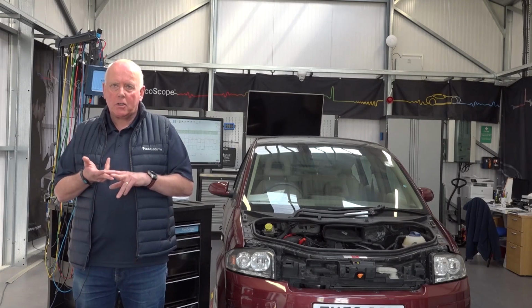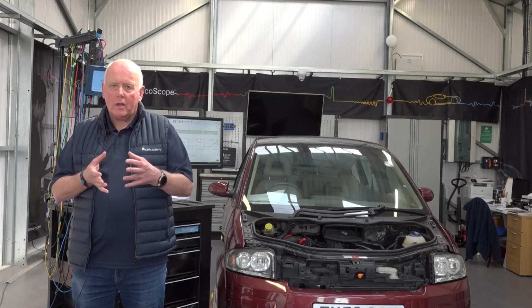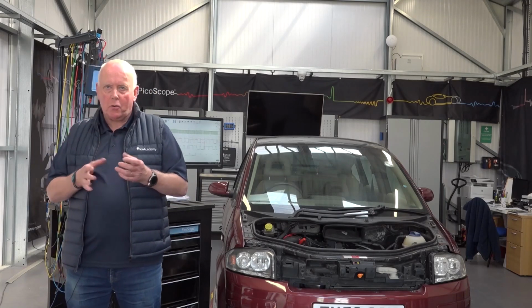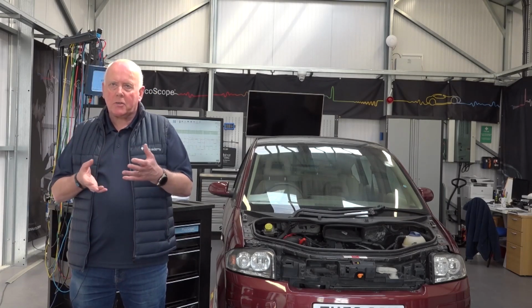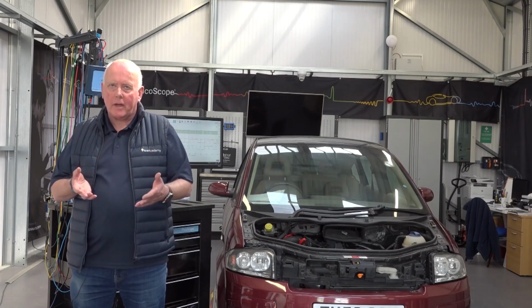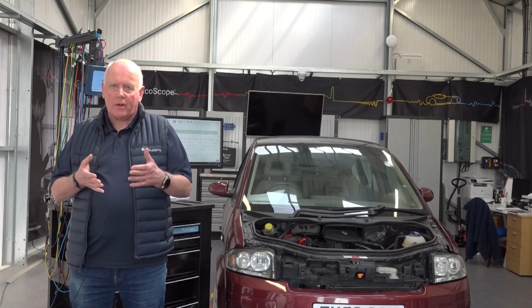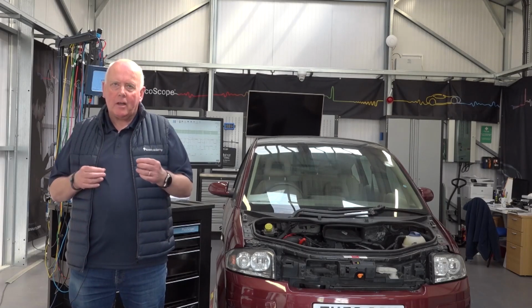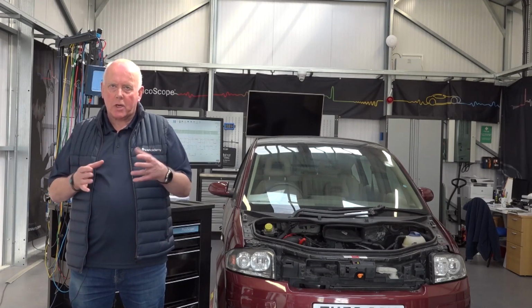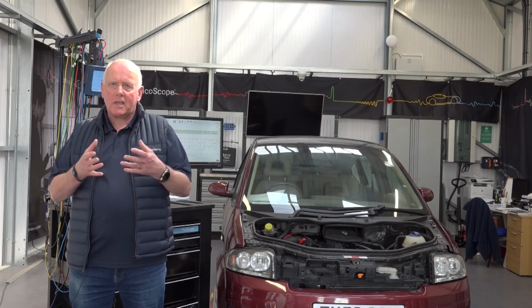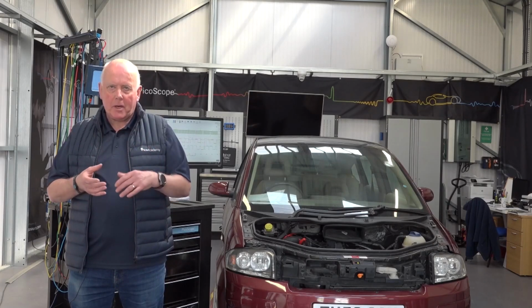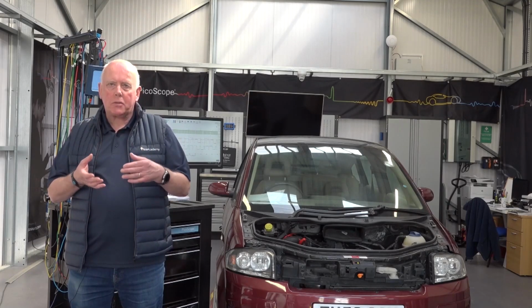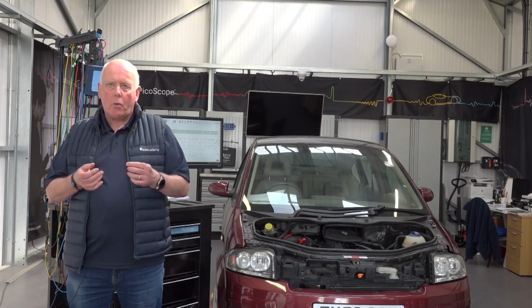And again, it is such a powerful tool to look at the waveforms, save them, look. One of the most basic questions that we normally get is, how do I know whether it's a good sensor? Look on the waveform library. Look to see how different Hall effect signals can be. And like everything, even between models, they'll change. So always look and save whatever you've got, put the information on the screen, and you can also then start to understand what each waveform looks like and have a better understanding.